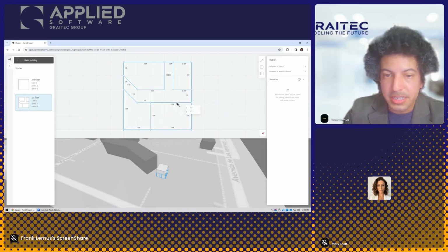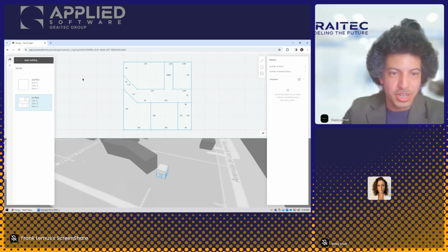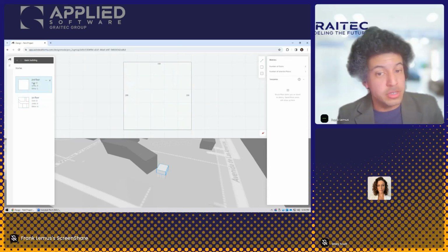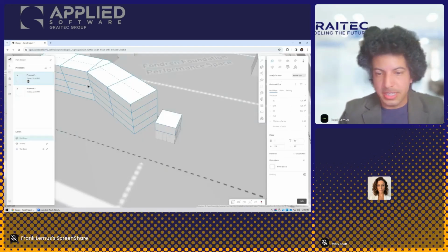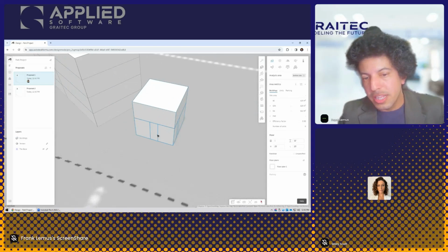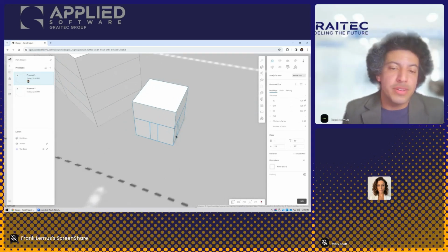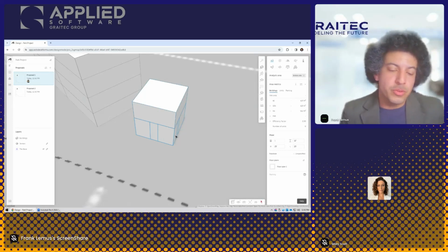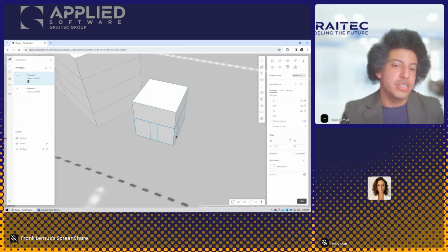And yes, these things get converted into walls. So no, you don't get to do doors out here. I have to find the first level. I could just do the same thing for level 2, and I won't, but I can do things for level 2 as well. I'm going to hit this little back button. You can see already the divisions. In Forma, they're just divisions. In Revit, they become walls. What we're doing in here is what we would have done in Revit with massing. These are just masses, basically.